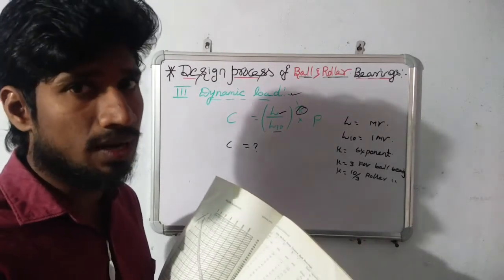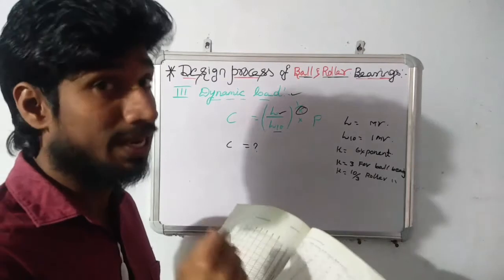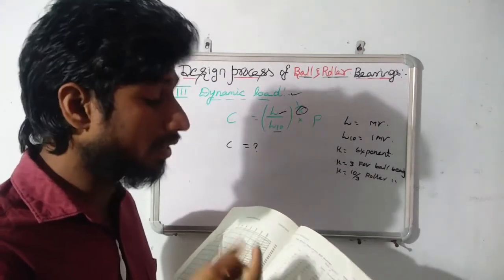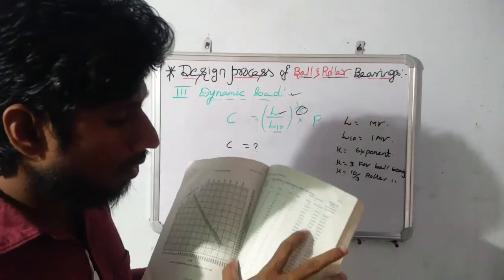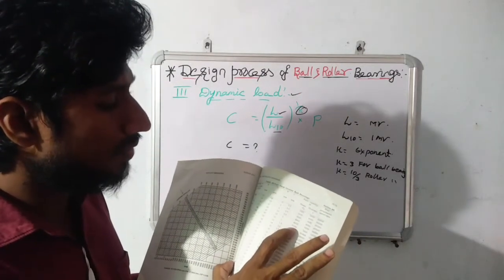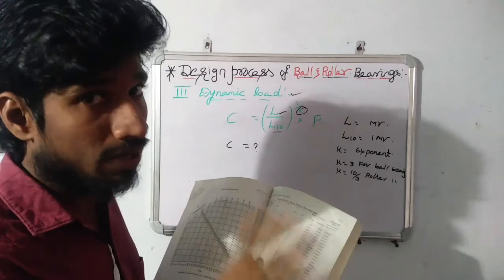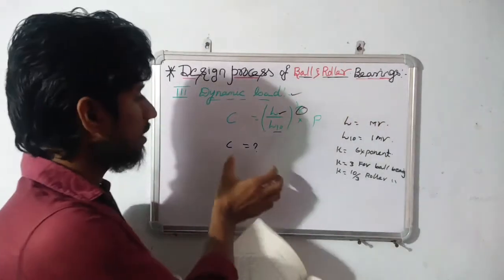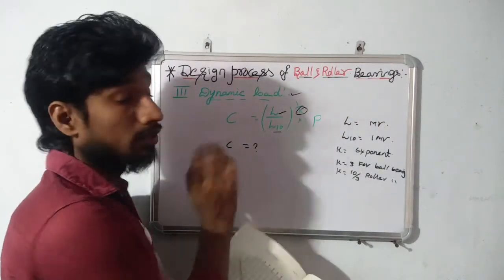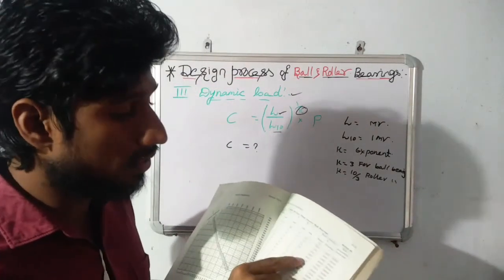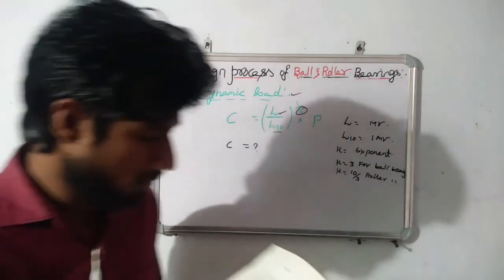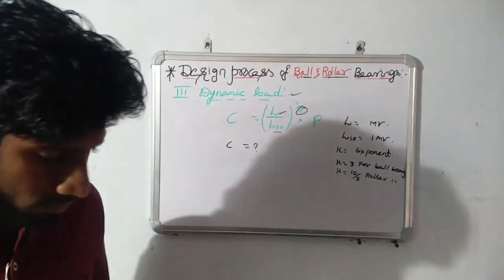With the help of this value, we are going to design a suitable ball bearing or deep groove ball bearing for that application. So let's see. Here I get the C0 value with the help of this consideration. Based on the dynamic capacity value, here we consider the static capacity value. Okay, go to the next step.